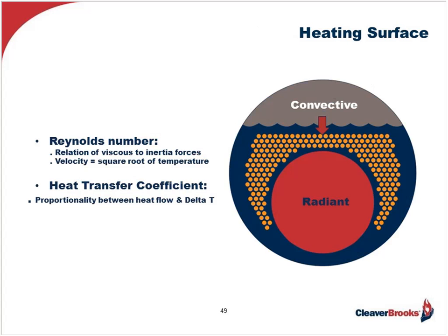The next thing I wanted to cover from an engineering perspective is the convective heat transfer in the boiler, which is that amount of surface which does not feed the flame, but is only exposed to the hot combustion gases. Now it's the orange area shown on the screen now and representing the fire tubes. This is the area of design where the heat transfer engineer is looking very closely at the design which maximizes